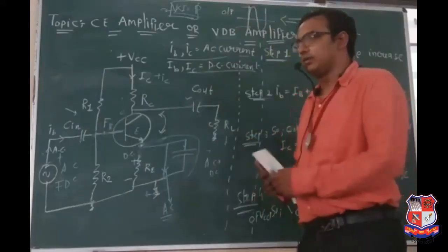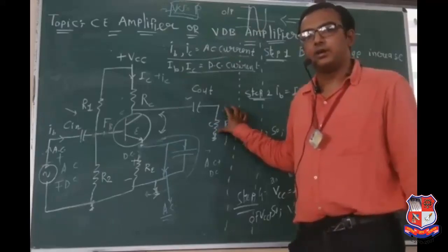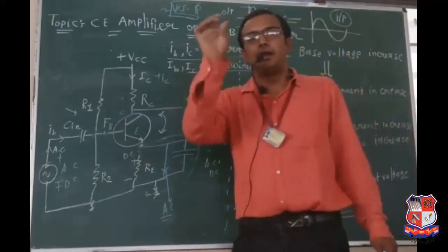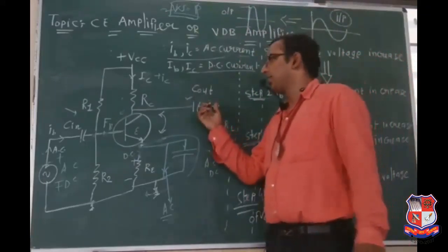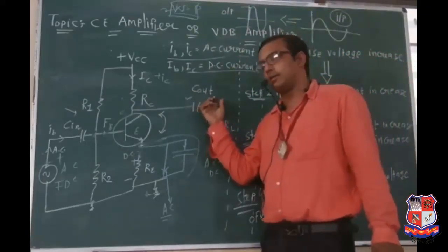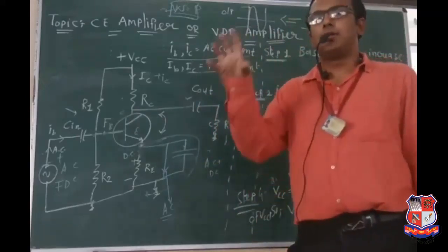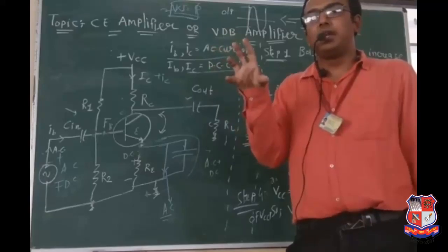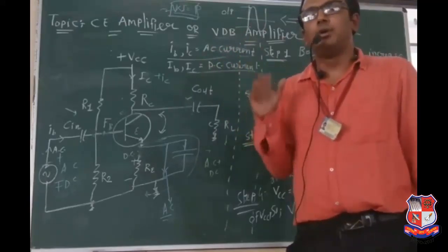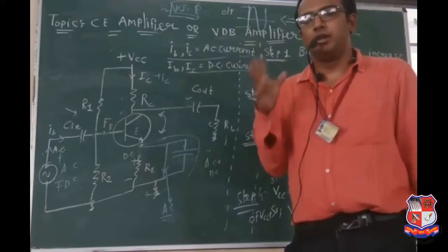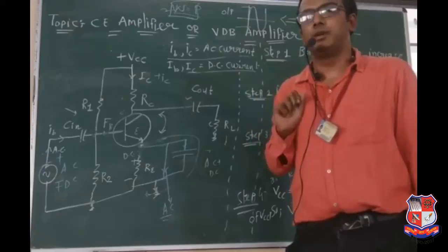In the output signal also, if we apply the DC signal to the loudspeaker, then the loudspeaker cannot give the exact information. At that time, the output capacitor is required. In real applications, in the loudspeaker, some type of hissing noise or unwanted noise, you will be able to hear in your ear. It indicates the DC voltage is present at the loudspeaker.